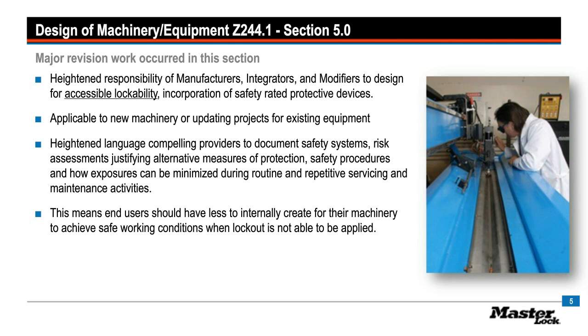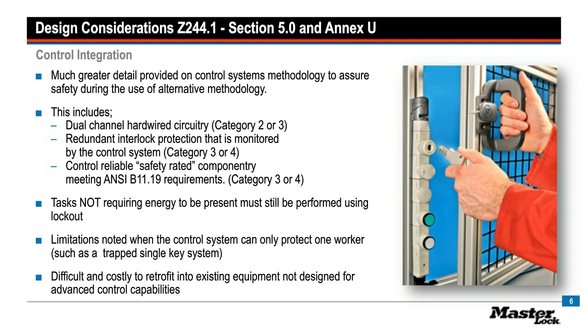Design considerations also took into consideration the advancements in interlocked and control reliable circuitry, and there is great detail provided in the Z244 Section 5 standard on a cross-reference of different interlock categories, risk ratings, and the ability to retrofit new technology into older machinery.